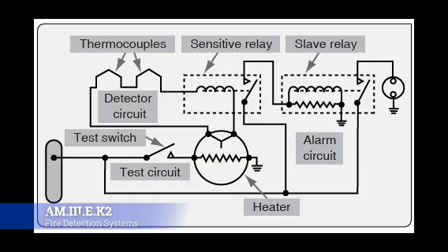Now, I won't go into all the relays and everything else, but the heart of the system are the actual thermocouple leads. They're made from a variety of metals depending on the maximum temperature to which they're going to be exposed. So there's a design decision made early on that, given the temperature of the location, they decide to use certain metals. Iron and constantan, or copper and constantan, are common CHT measurements, like on your CHT, which is your cylinder head temperature. Chromel and Alumel is another EGT one that's very common in turbine engines, which is where we're kind of focused.